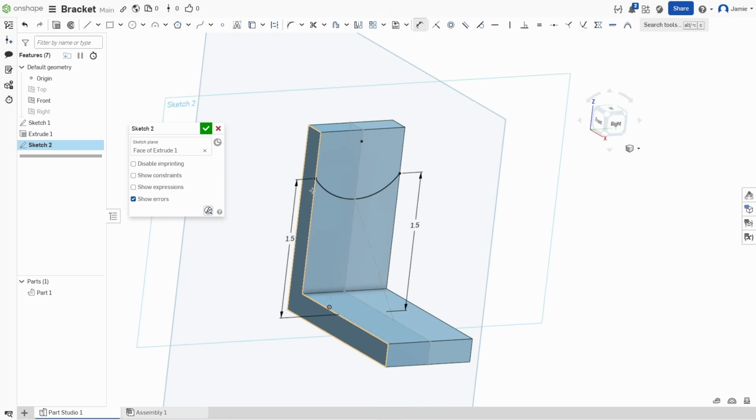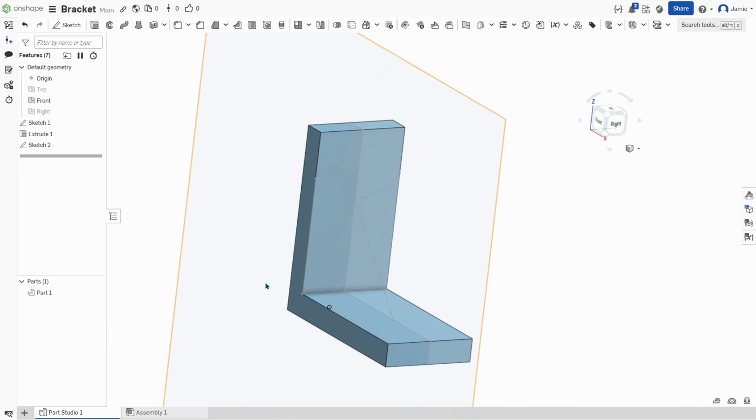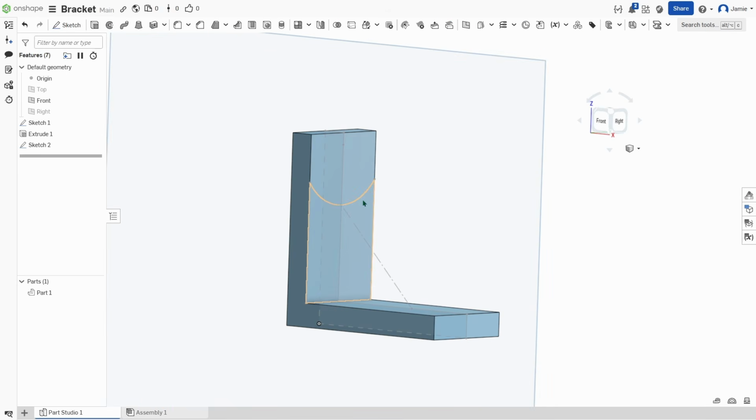So we are going to take this and extrude it down. So let's create a body out of, finish the rest of the body. So click on that line, click here, all the way down, over. Okay, it's fully constrained. Green check, we finished that. So now we can take this body here and we can extrude it on this construction line.